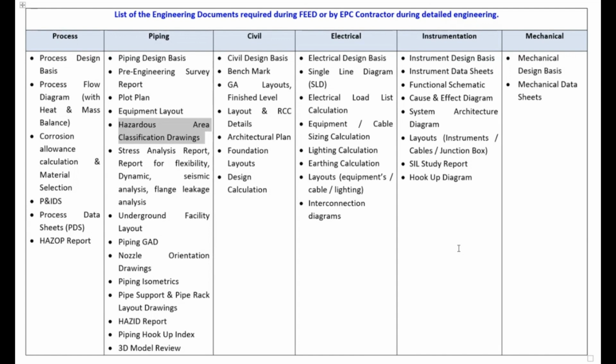It should be explosion proof, flame proof, and one is called weatherproof, correct? So suppose there is a light at the gate of the plant, and that is in a safe area, not in the hazardous area. So it need not be an explosion proof light, okay? Weatherproof is sufficient. What is weatherproof? It should be protected from water and dust, IP, okay?